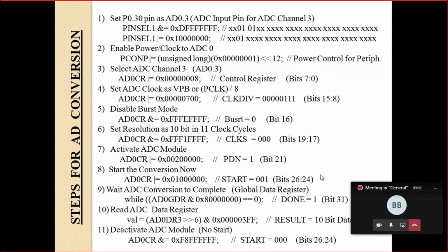Now you are going to configure the ADC in such a way that I connect a sensor to channel 3 of the ADC. Which is the simplest sensor you can think of? Potentiometer. All of you have seen potentiometers, in volume controls and other knobs on an amplifier, or a dimmer. When you turn the potentiometer knob, the output voltage will change.